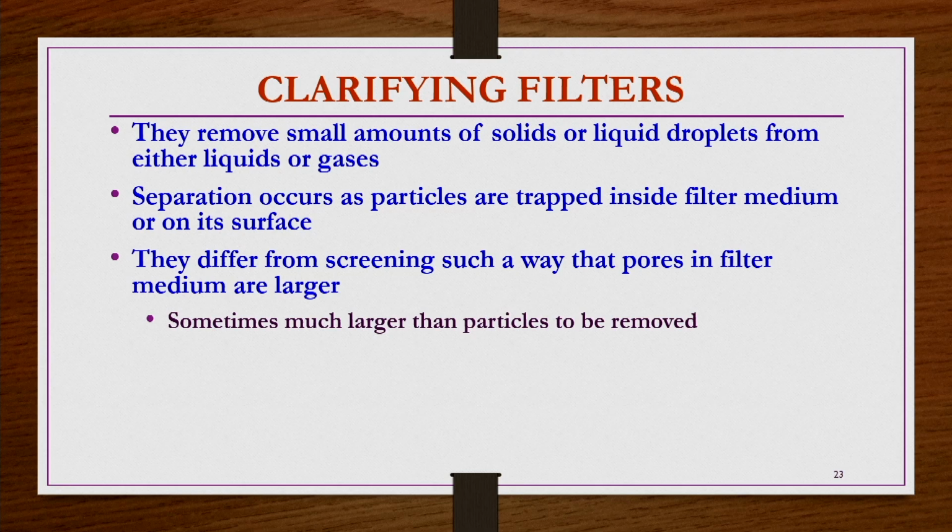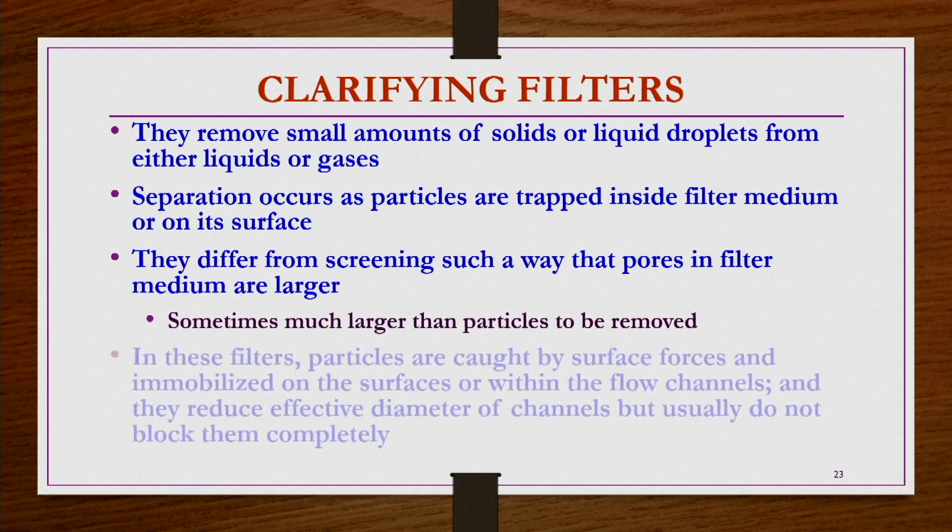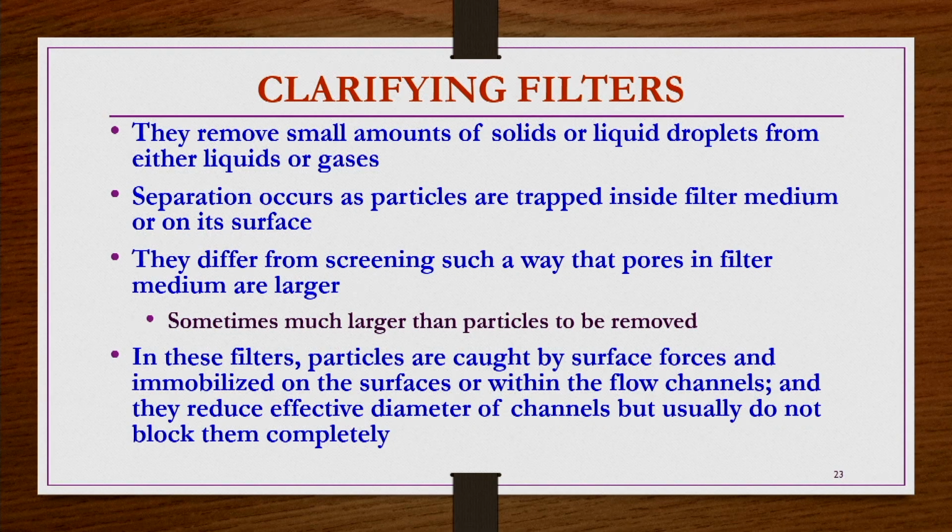In whatever the clarifying filters, the pores are there, sometimes they may be much larger than the particles to be removed. However, despite that, separation takes place, almost complete separation takes place because of the deep bed of this pack of filter medium that we use. In these filters, particles are caught by surface forces and immobilized on the surfaces or within the flow channels, and they reduce the effective diameter of channels, but usually do not block them completely.